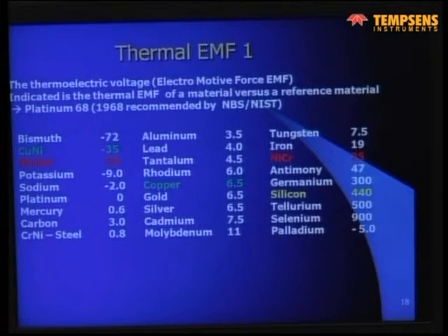You can imagine that even small amounts of silicon in a noble metal thermocouple will produce highly erroneous measurements. Approximately 1 ppm silicon in a noble metal thermocouple produces an error equivalent to half a degree centigrade, even 1 degree.